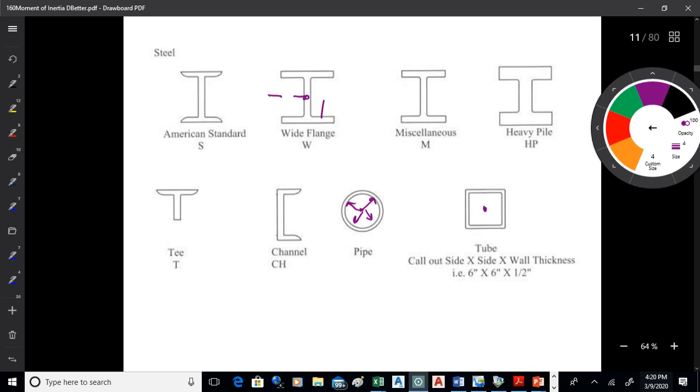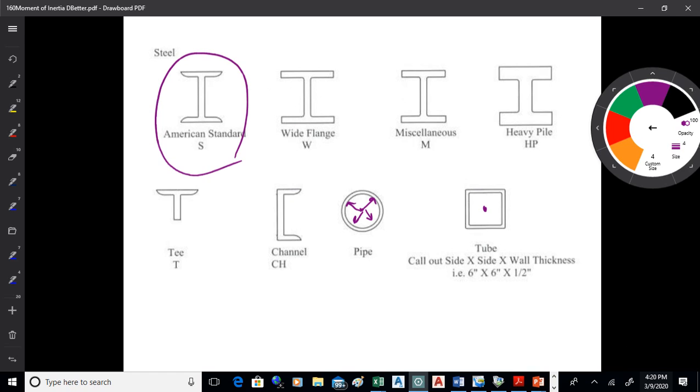Now, if you look at the beams from 100 years ago or so, they were American Standard. That was the shape, like that. Okay, narrow flanges. So what we have on these beams is in the middle, holding it together, the web, and then these things on the extreme ends are called flanges. American Standard beams had relatively small flanges that were rounded. Filleted is the term.